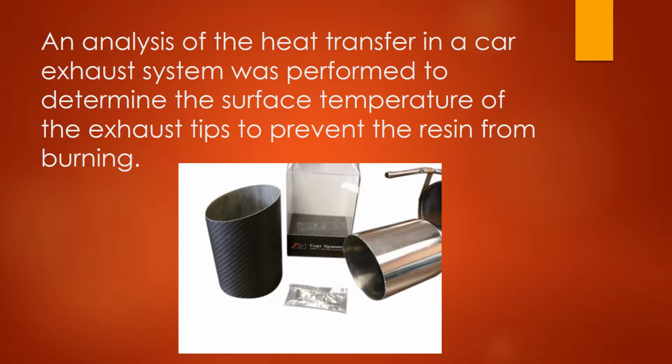composite. The epoxy chosen for this part can reach a temperature of 370 degrees Fahrenheit and maintain the required material properties. The purpose of this analysis is to create a model that predicts the surface temperature of the exhaust tip to determine if this epoxy will burn.